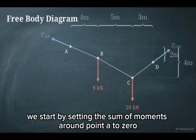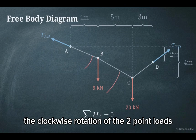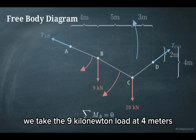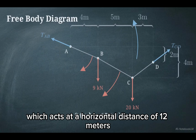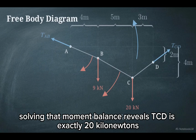We start by setting the sum of moments around point A to 0. This requires us to balance the clockwise rotation of the 2 point loads against the counterclockwise pull coming from the support at point D. We take the 9 kilonewton load at 4 meters and the 20 kilonewton load at 9 meters, then set them against the tension of segment CD, which acts at a horizontal distance of 12 meters and a vertical distance of 2 meters. Solving that moment balance reveals TCD is exactly 20 kilonewtons.